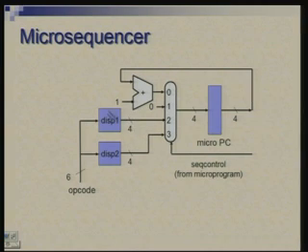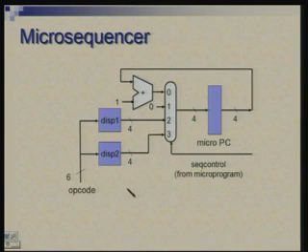Once again you can think of these as small tables. Depending upon the opcode value, you want to pick up one of those 4 possible addresses. Here, depending upon opcode, you want to pick up one of the 2 addresses. So, these could be small ROMs or small PLAs. So, we leave that here. The main point is that there are a very small number of ways in which you need to determine the next address, and a few bits in the microprogram will control this multiplexer.